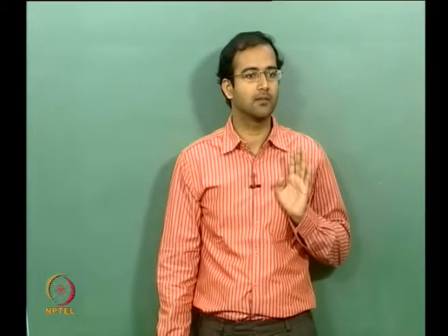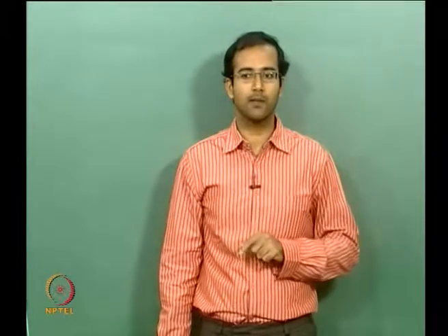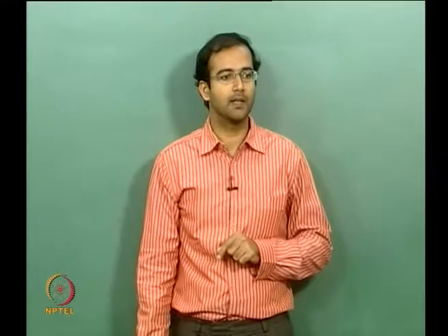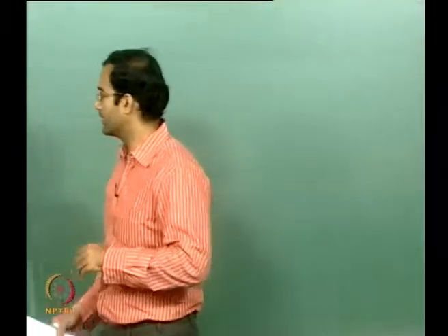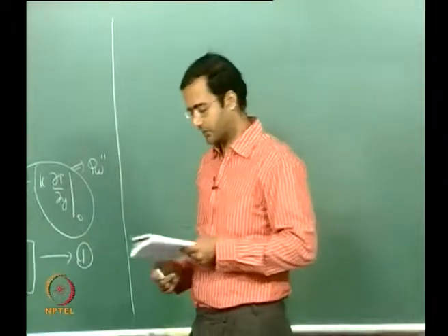So we cannot guess any velocity profile, but we have to take the exact profile as it is, because if we had guessed a profile and applied the momentum integral, that will be valid only in region 1, and that too in the developing section. Once it is close to becoming fully developed, those profiles are not valid, and we are looking at region 2 now. So we cannot guess anything for velocity, we have to take the exact parabolic profile.